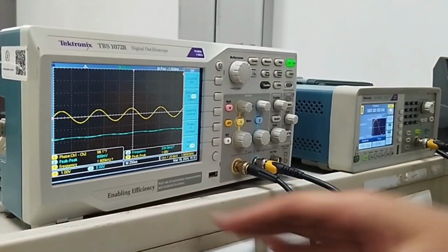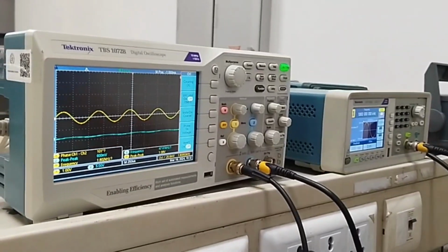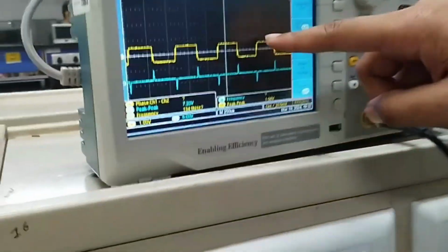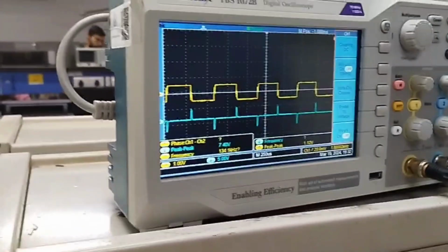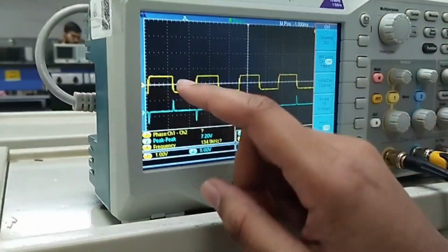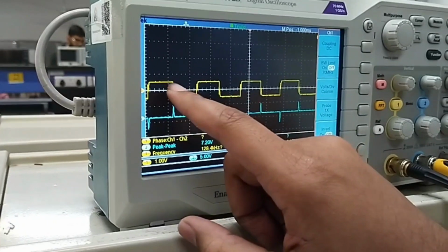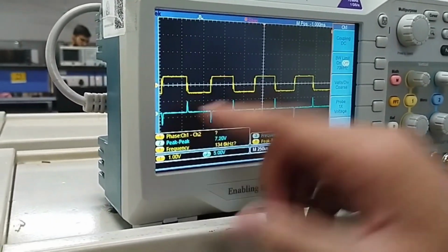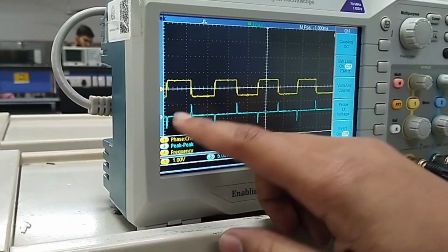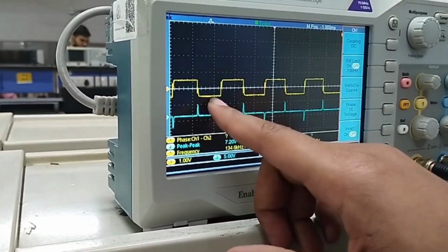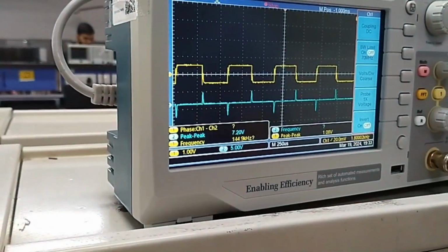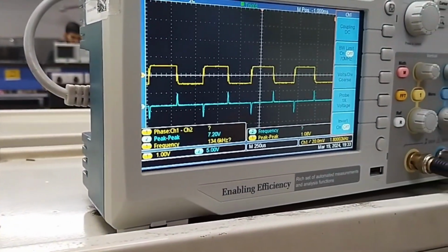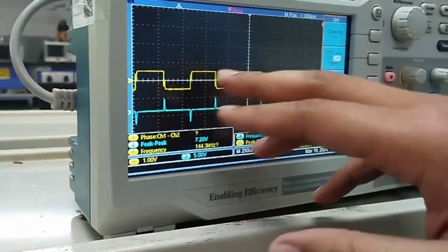So we have done it for the sine wave. Now we will do it for the square wave. So when I change the input to the square wave, this will be the input and output. So the differentiator generally differentiates the input. When there is a constant value in the square wave, the differentiation of a constant is 0, so it is showing 0. And when there is a sudden change in the graph, we'll see a spike because of the change, which is slope, and that is itself the differentiation. So these are the spikes where the sudden changes occur in the square wave.